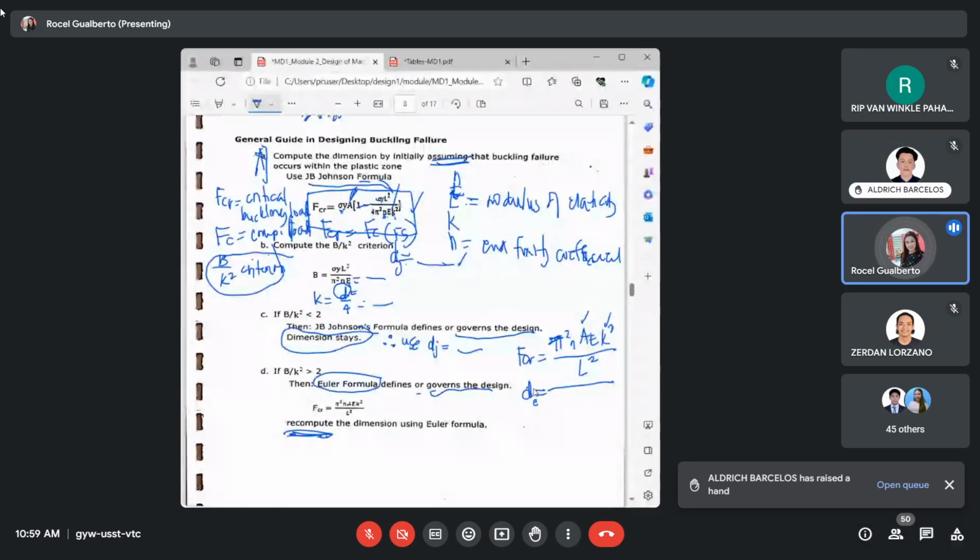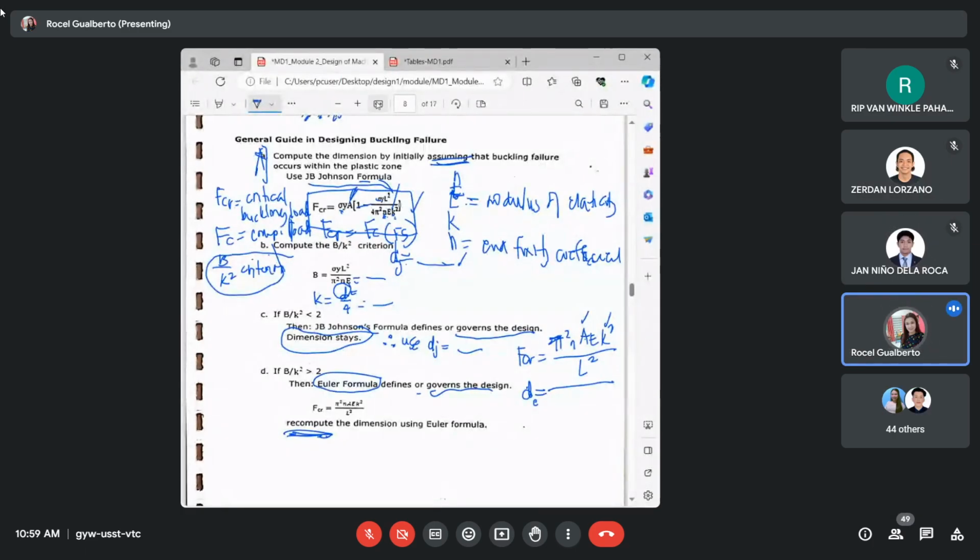Okay, so yan po yung procedure na atin na i-apply, okay? Again, uunahin po natin is the J.B. Johnson using an assumption, okay? Failure at the plastic zone, okay? So you use the J.B. Johnson. You'll have your answer, okay? Yung answer po nun, you need to check that using the B over K squared criterion. So sa K po, isa-substitute po natin yung tinetest natin.